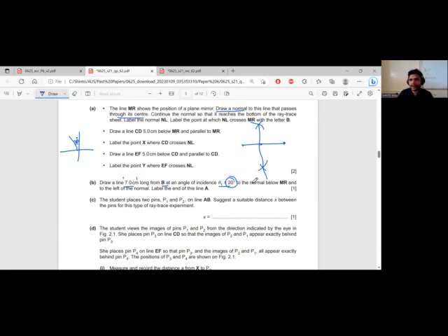And this is the protractor that you're using, and all the protractors that you have seen have a least count of 1 degree, meaning you cannot measure anything lower than this. So you can make an error of either +1 or -1 to this 20. So appropriate labeling should be 20 plus or minus 1 degree.